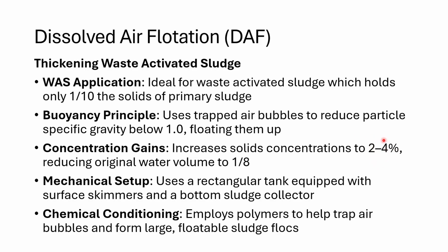I'm sorry, not by, but it's going to increase solids concentrations to 2 to 4%, and that's going to correspond, if we use our rule of doubling solids increases, to reducing water volume by half. Well, putting our solids concentration with dissolved air flotation in this process to 2 to 4%, we're going to reduce the water volume by 1/8 or 12.5%.